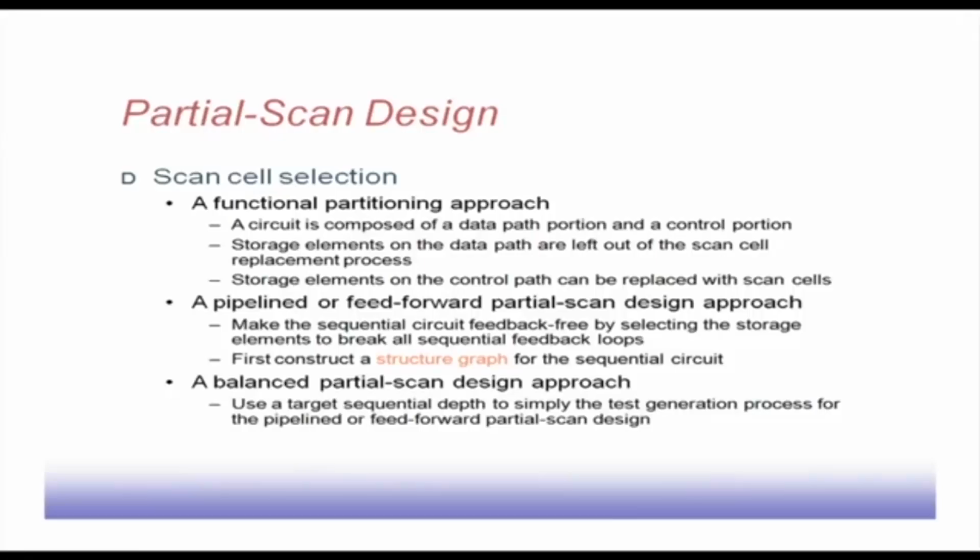So, that has to be avoided, because it creates a loop in the reasoning process. Whenever we have a sequential circuit, we want to make it feedback free by selecting the storage elements to break the feedback loops. For that purpose, one structure graph is constructed for the sequential circuit. We will see how to do this.